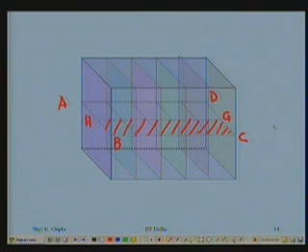Let's cut the bonds on this part of the plane now, that is BCGH. This we cut the bonds, and give the top part again a push by one interplanar spacing, but in front. The back, since you have not cut the bonds, you will not be able to do it, but in front you can do it. Push them so that this atom which is bonded here will go and bond with that. Like that it will go on, and once you have done this push, let's see what happens to the configuration after the push, and after allowing the bonds to form again.